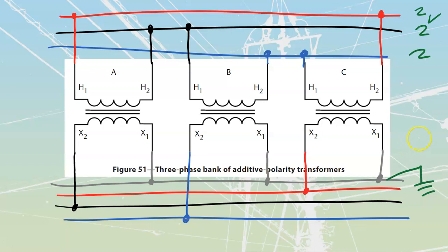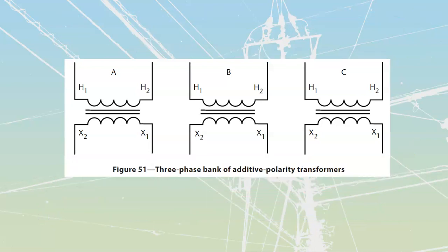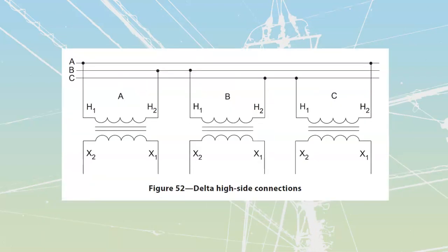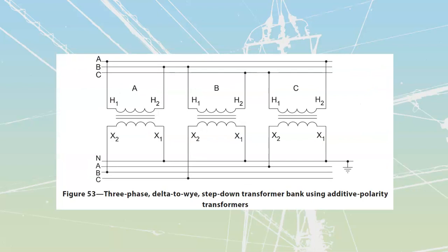I see that I have got 3 connections onto this neutral. That's a good Y. And I see that each of my lines have only got 1 connection each. That's a good Y as well. The next couple of diagrams that they had inside of here show the exact same thing as what we just